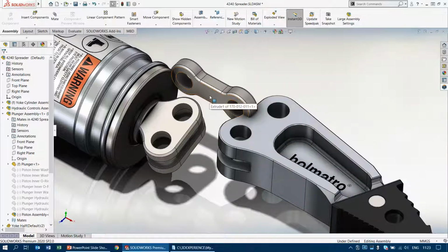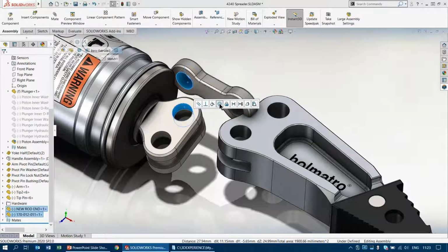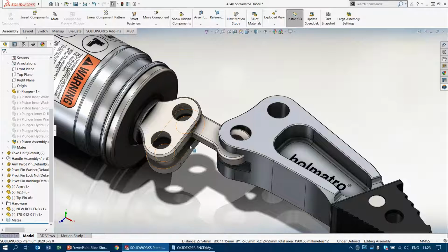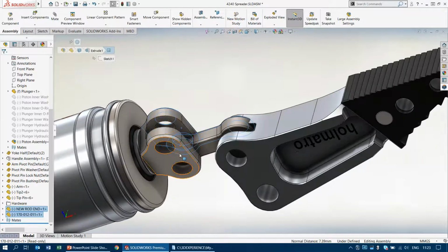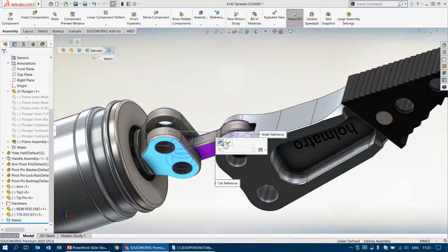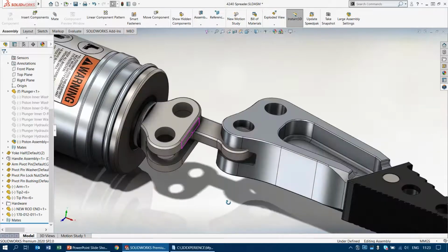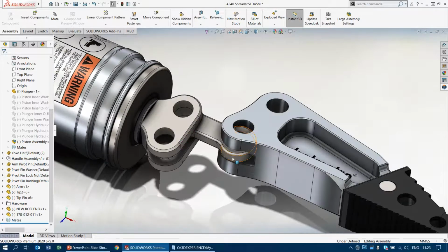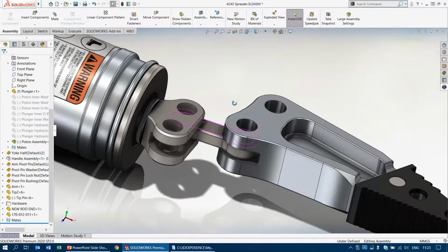So now from here, I can simply drag and drop right inside of SOLIDWORKS. It brought it inside of SOLIDWORKS, and now I'm simply going to do some assembly, right? So I'm going to make that concentric, control select these four faces. If you're not familiar with Mate, this is super awesome, goes really quick. And then the last thing I want to do is probably put this and this concentric, control select, put it concentric, and I'm done.